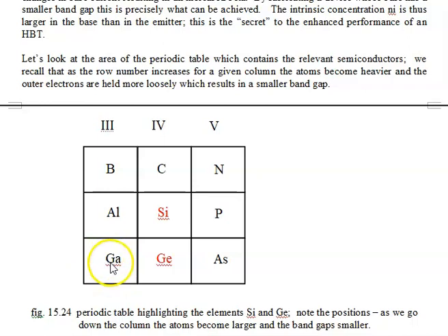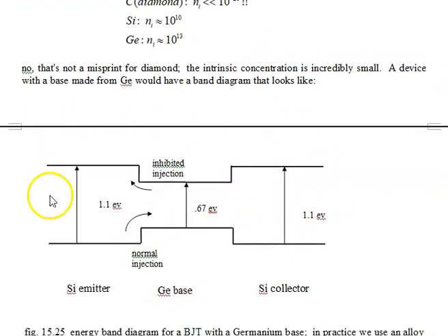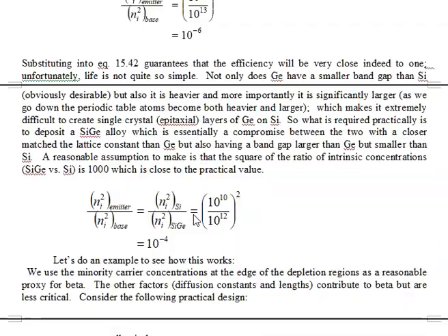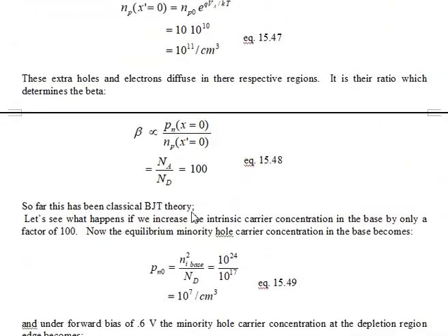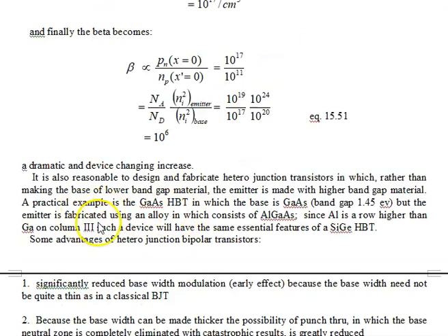If you replace some of the gallium with aluminum in the emitter, not in the base, we're going to get a wider band gap, 1.5, 1.6, something like that, but it's the same structure. Large band gap in the emitter, smaller band gap in the base, and we can do exactly the same thing and have a rather enhanced performance by replacing some of the gallium with aluminum.